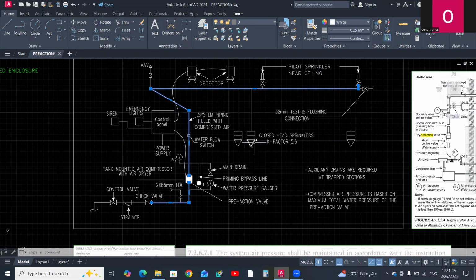Each sprinkler has a responsive heat element, which explodes in case of fire, and water flows through the nozzle or sprinkler. So in non-interlock, you can activate the system either by the sprinklers or the detection system.